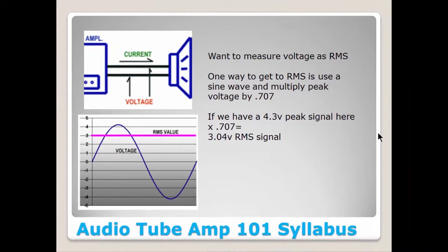Okay, remember earlier I showed you that power equation and I said when V is a DC voltage. Well, we've got a sine wave here that's going up and down, varying constantly. It is not a DC voltage, but there's a way to get close to the DC equivalent value of that signal. Remember, DC is just a constant voltage going all the way across, and this sine wave is not. But one way you could approximate the value, from this point in time right here, remember the x-axis here is time, up to this point in time, is you could chop off some of this up here and start filling in, almost like with sand, a little bit over here and a little bit over here. You keep chopping off more and more till this top part is gone and it has filled in the sides till this thing is completely flat from there to here.